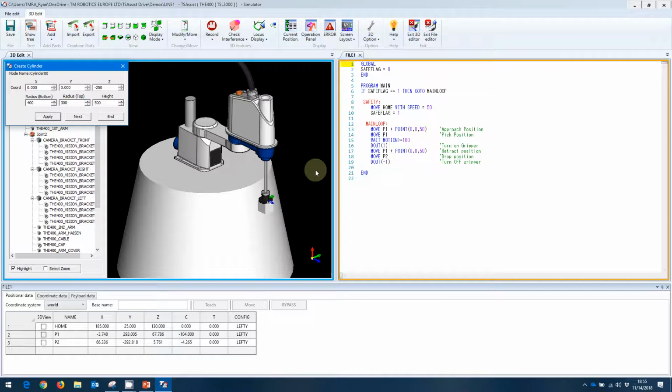Now what I'm going to do as well is I'm going to drop that down an extra millimeter, so it's going to be 251. The reason I do that is in a few minutes we're going to go through the interfere check functionality, and what that's going to look for is any two shapes that are touching. If the robot's actually touching the base, it's going to throw off some false positives. So we're going to give ourselves an extra millimeter to be safe. So we'll apply those changes.